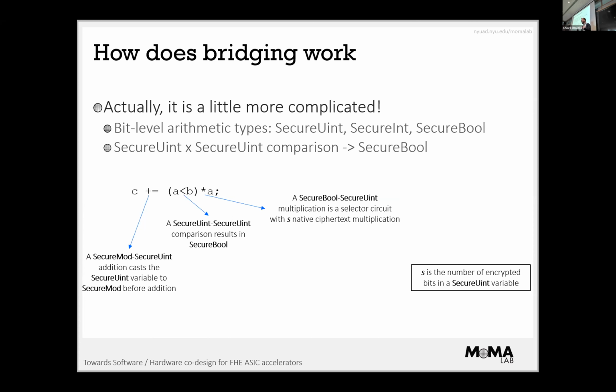As you can understand, the range here is important. In regular computers, we very easily say 32 bits, 64 bits. It's the same. Here, every bit you add adds performance overhead. So if you can constrain, for example, to 8 bits your computation, then that's great, right? Even 9 bits, right? If you don't need 16 bits, don't round it up. Stay to 10, stay to 11 bits, because every bit added makes a big difference in performance.